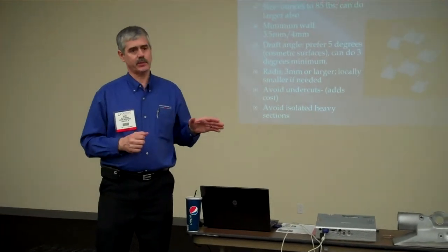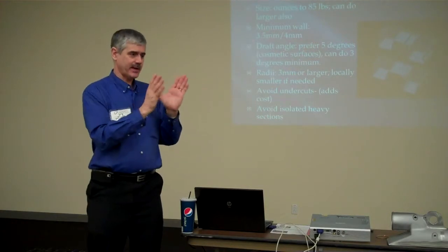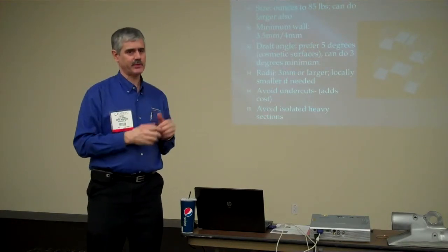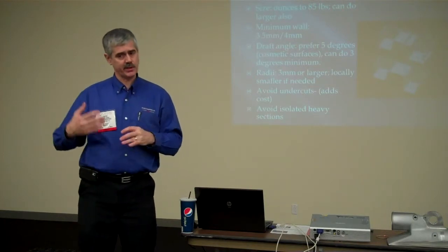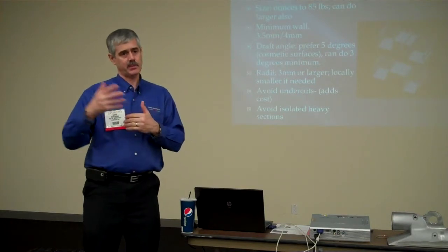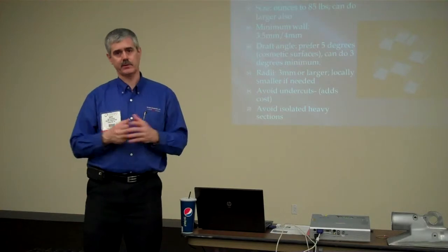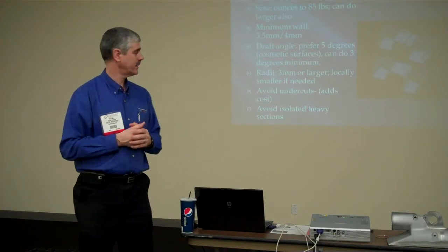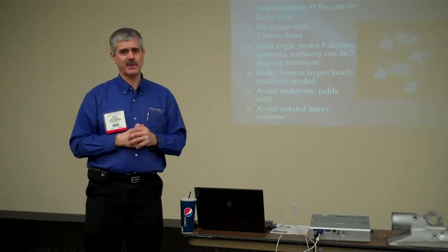So from a design standpoint, if I'm designing a part, that's a problem, putting draft angles on there. It's a lot easier to design square boxes than tapered walls, right? And machining datums is another area where if we're machining the part, we like to have draft on a datum because it's repeatable and reliable. But machine shops would rather have it be square and not have the difference of the draft angle affecting their CMM check or their location. So draft is a good thing, but it's hard to convince people of that sometimes.